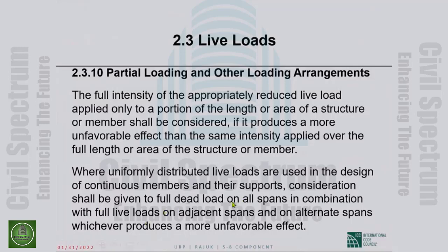Where uniformly distributed live loads are used in the design of continuous members and their supports, consideration shall be given to full dead loads on all spans in combination with full live loads on adjacent spans. That will give you the highest support moment, and on alternate spans, whichever produces a more unfavorable effect. So this so-called pattern live load is a requirement of the code, but more and more we don't spend time doing that.